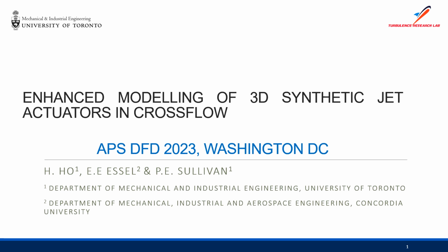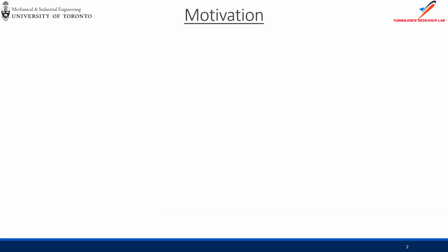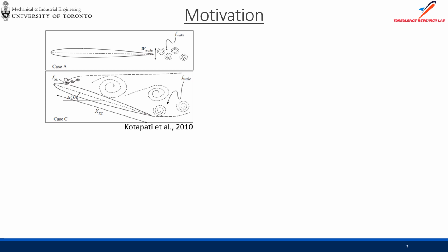Today, I'm going to talk about some of the different ways of modeling a 3D synthetic jet actuator, also known as SJA, in a crossflow. So, starting with a bit of background, the underlying physical phenomenon that we're trying to combat is flow separation.